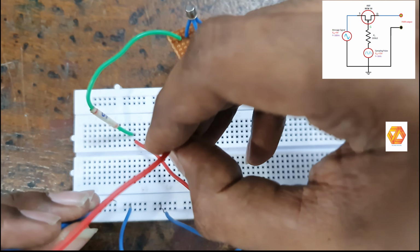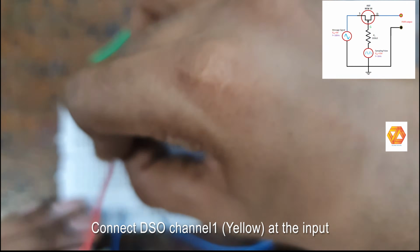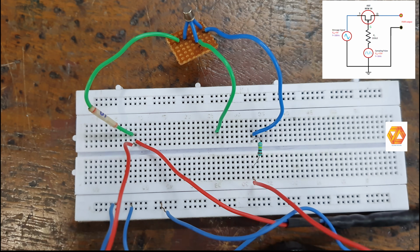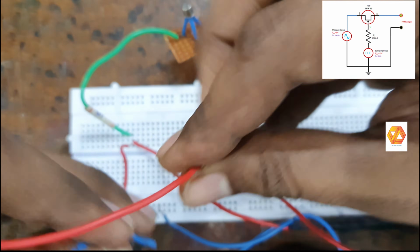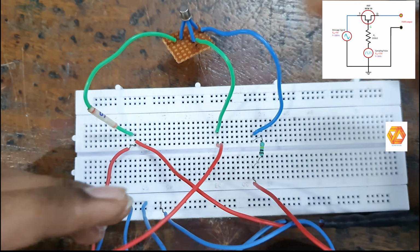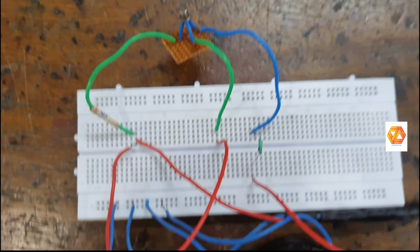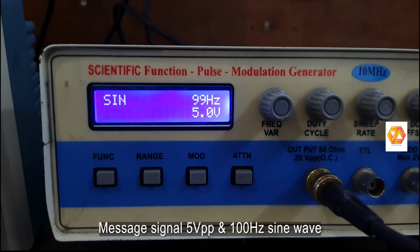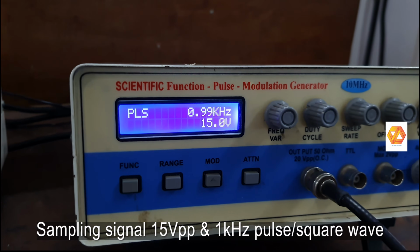Now the input message signal and sampling pulse signal are both connected to the circuit. In order to observe the waveform on a DSO, connect channel 1 of the DSO to the input and then connect DSO channel 2 to the output. Here we are taking the output from the drain terminal of the BFW 10 FET. Now the connections are completed. This is the message signal, sine, amplitude 5 volt and frequency 100 hertz. This is the sampling pulse, 15 volt amplitude and 1 kilohertz frequency.